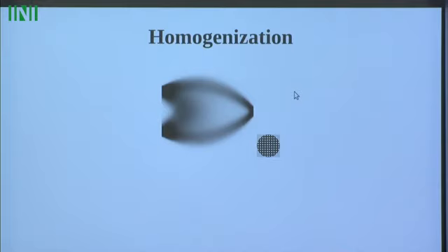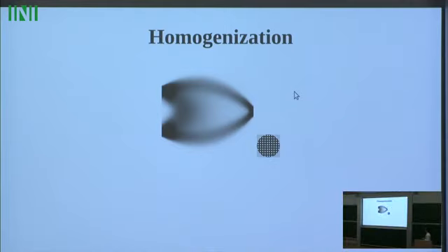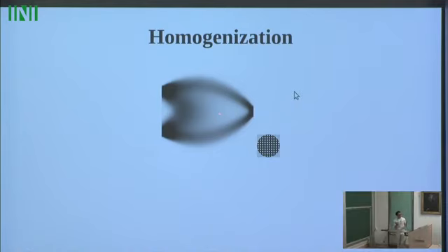You have no way to build this shape. So the purpose of dehomogenization is to go a little bit backward, meaning that it is post-processing of the homogenization method. We start with the optimal composite, and what we want to find is a sequence of changing shapes that converges towards the composite shape.